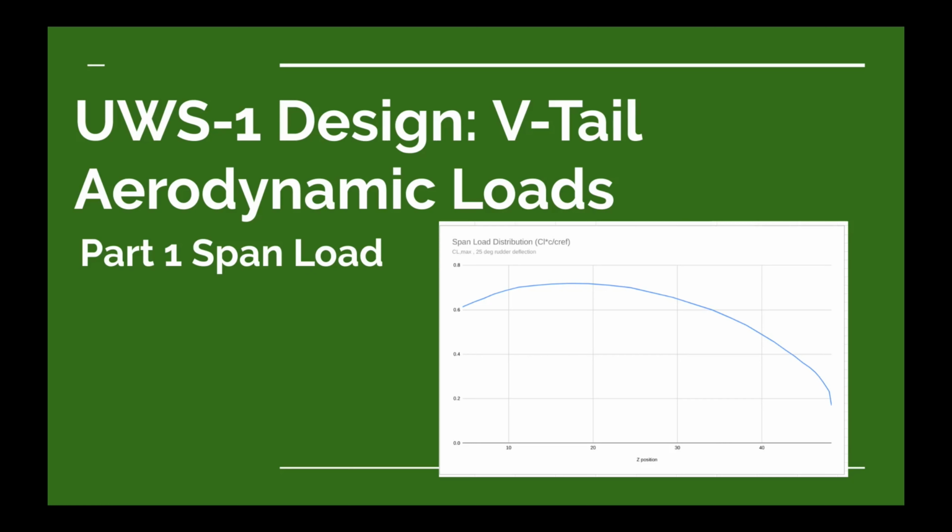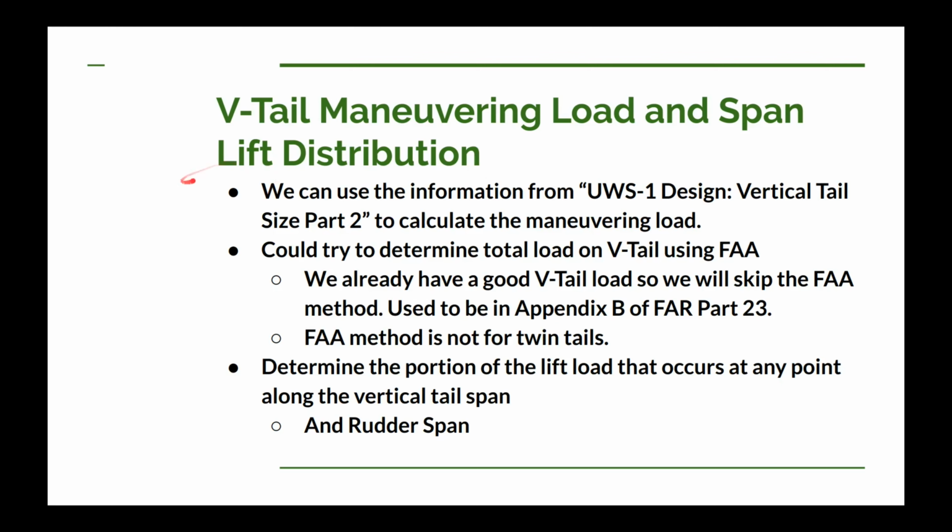After that, we'll switch over to using OpenVSP and VSPAero, which is a subpart of OpenVSP that is used to do aerodynamic calculations. Once we get that done, we'll have a span load distribution to do some other load calculations. What we want to do is calculate what the span lift distribution is at our maneuvering speed. So we'll get a maneuvering load on that vertical tail.